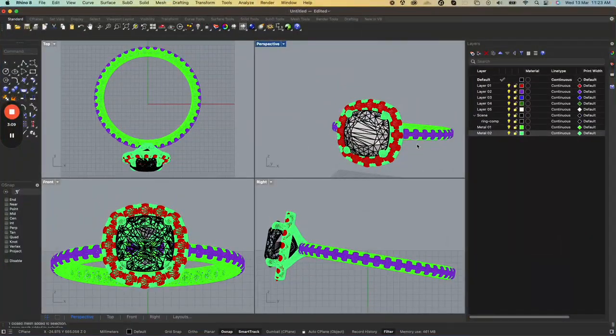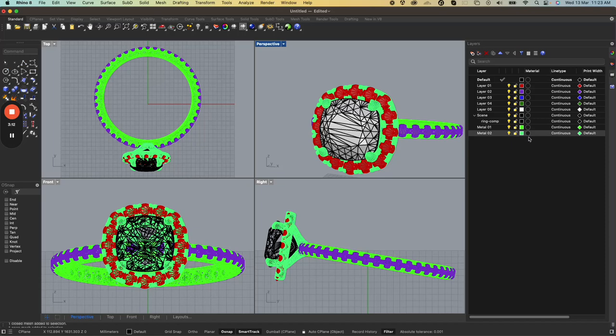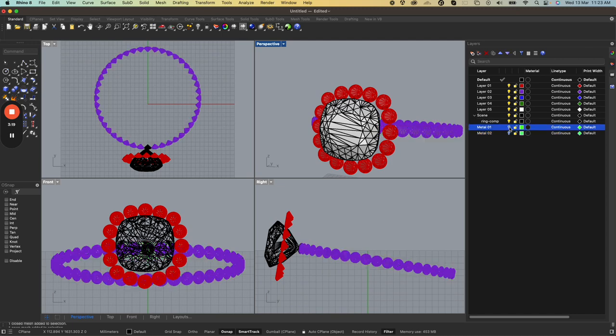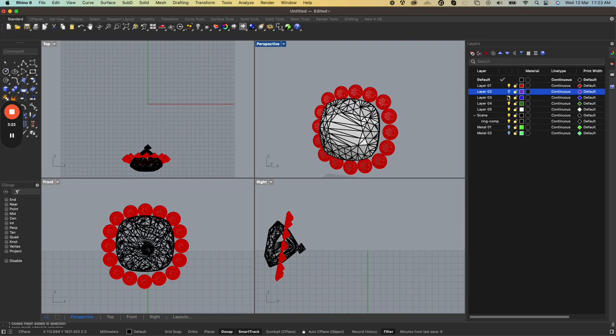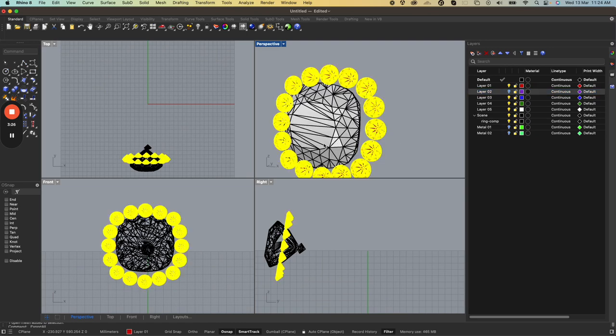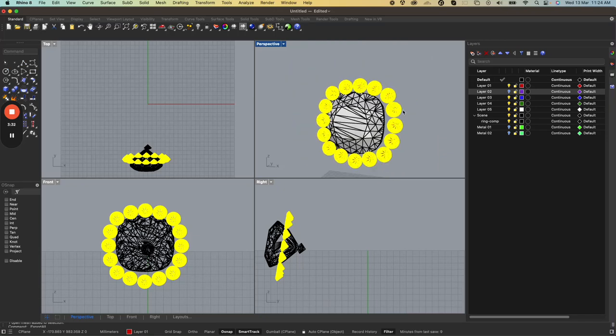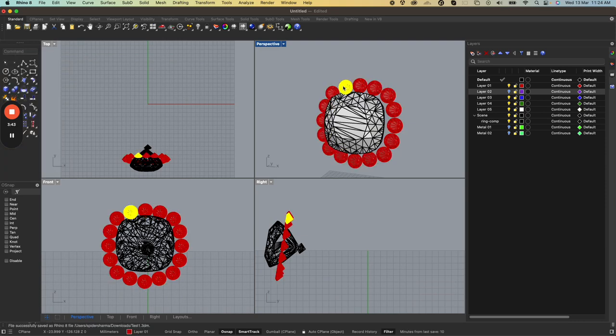Okay, now let's take a look at some other things. Using layers, you can also hide and unhide an entire group of objects. Now if you select these parts, they are all grouped under the layer 2 here. If you want to ungroup these objects, you can write a command called ungroup, and now you see that they are separated out. This way, once you have ungrouped, you can assign a different layer individually to these objects.